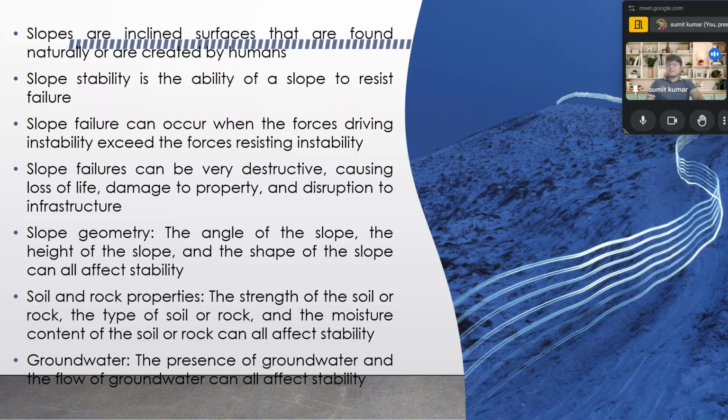Soil and rock properties are very important. As we go ahead, we see some interrelation regarding the factor of safety for the infinite slopes. We found that the infinite slopes behave differently at different soil properties. There, we also see the effect of the water table as well. As I have said many times, water is the biggest enemy of the soil in one way or the other. If the water table is not there, 50 to 60% of the problems associated with soil get eliminated. So those aspects we also take into our study as we go ahead.